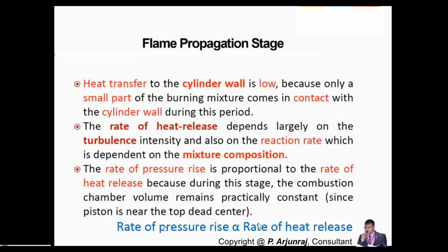So this is where it is very much important here. And how much the pressure is going to increase also depends on the heat release rate, okay? This also depends on the volume of the combustion chamber, so all this design will vary. I am not going with respect to the configuration point of view, because if I do, companies like Maruti, Hyundai, Tata, Mahindra, every company will have their own configuration. I'm not going to touch on that, but here I'm going to touch only the basics or the theory behind